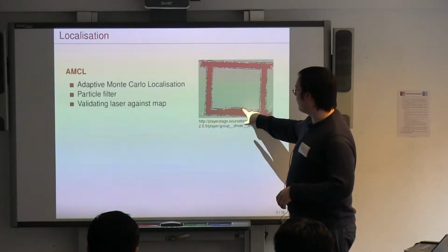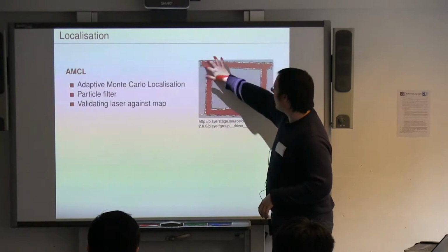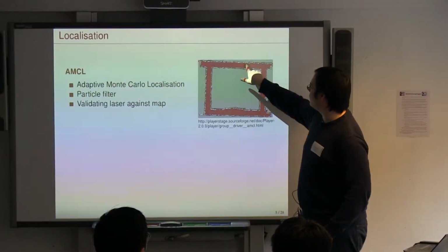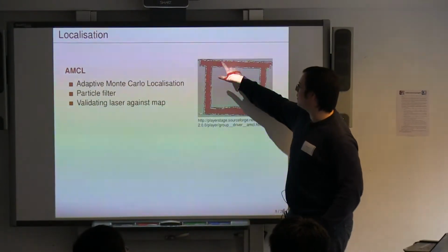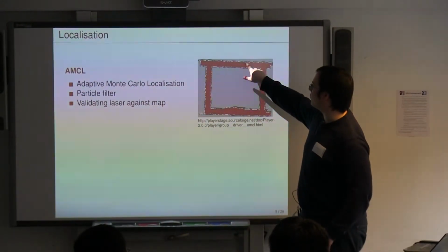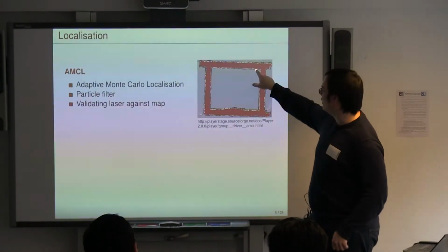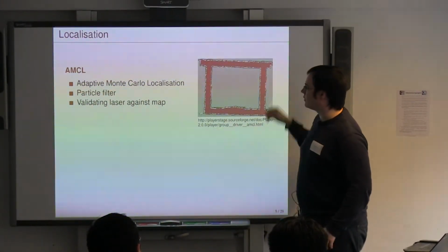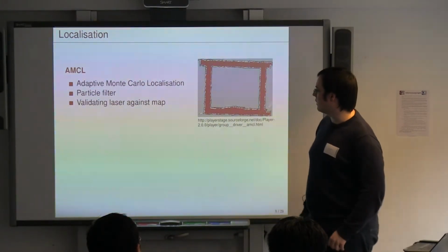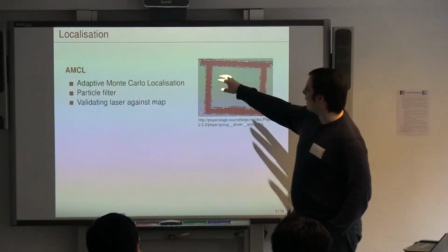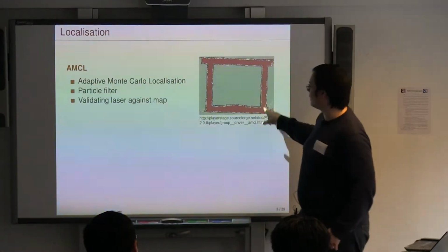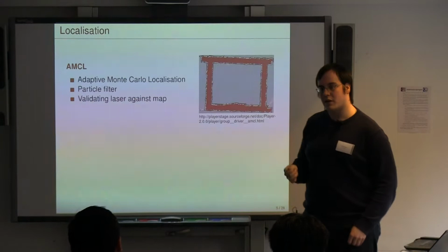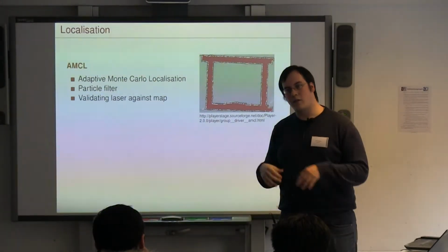Here on the right side, for example, we have these black outlines, which are the map. The bright part, which you can just see a little bit, is the inside of the map, the known area, which is thought to be free. Gray is typically the unknown part. And the red part is the hypothesis of the Monte Carlo localization, where you believe your robot is.